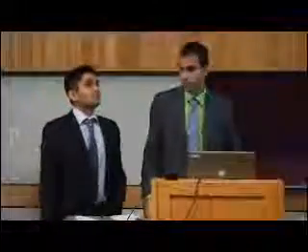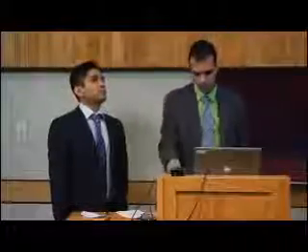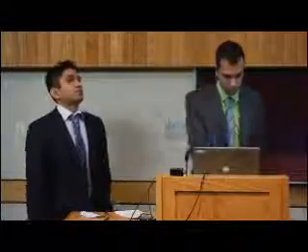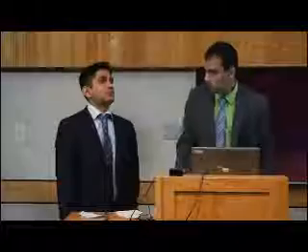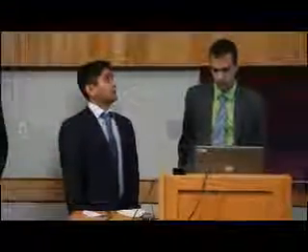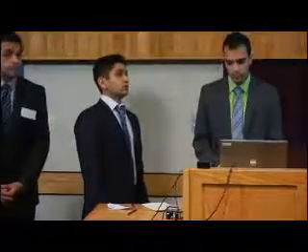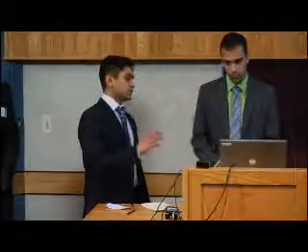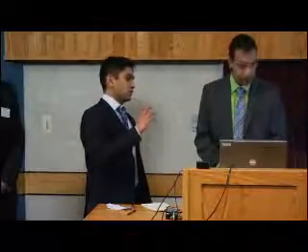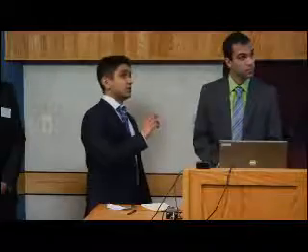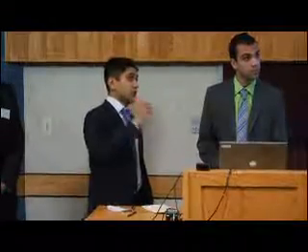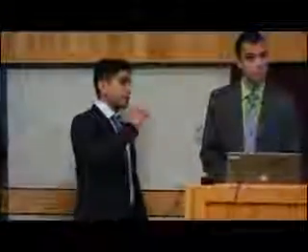Sure. How does the carbonation cell work in effectively absorbing carbon dioxide? That's a good question, because that's the key part of our system, because we want to make sure that the carbon dioxide stays in the water. The pond itself is only 30 centimeters in depth, but the carbonation sump is 1.2 meters in depth, and it's located inside the pond.